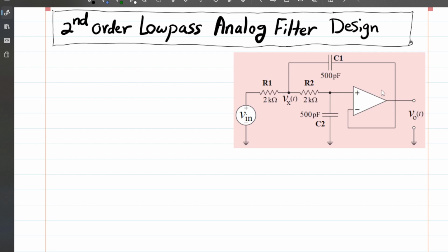Since again this ideal op-amp is in buffer negative feedback, whatever voltage appears at the positive terminal, which is zero, also appears at the output. So irrespective of Vin applied, at high enough frequencies Vout will be zero. That's an indication that this system is not passing high frequency components and is only passing low frequency components. Therefore, it's a low-pass filter.